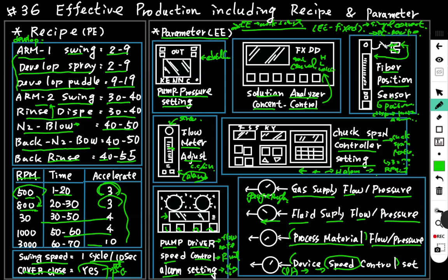It even transfers the signal to the computer of the factory so the factory side can receive this parameter signal, and engineers sitting at the office can watch the values or use them in the SPC chart to monitor it.